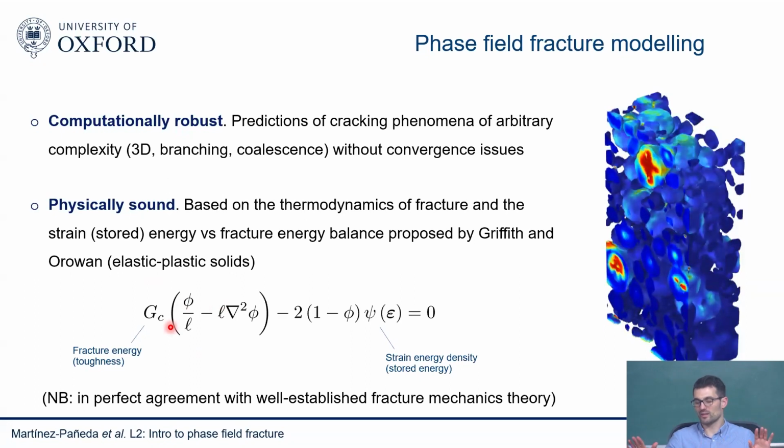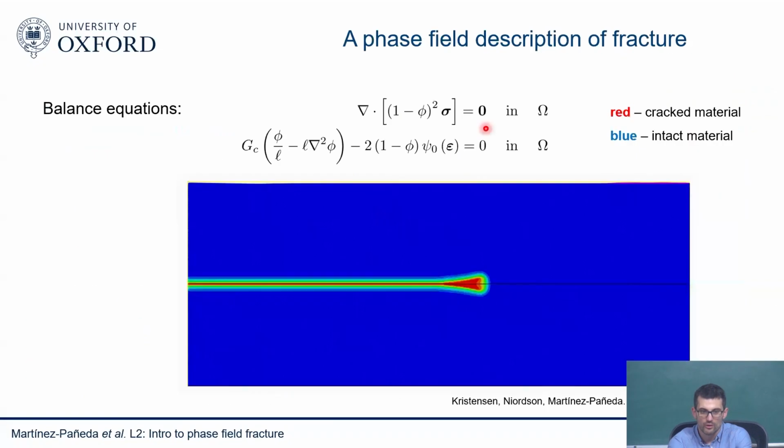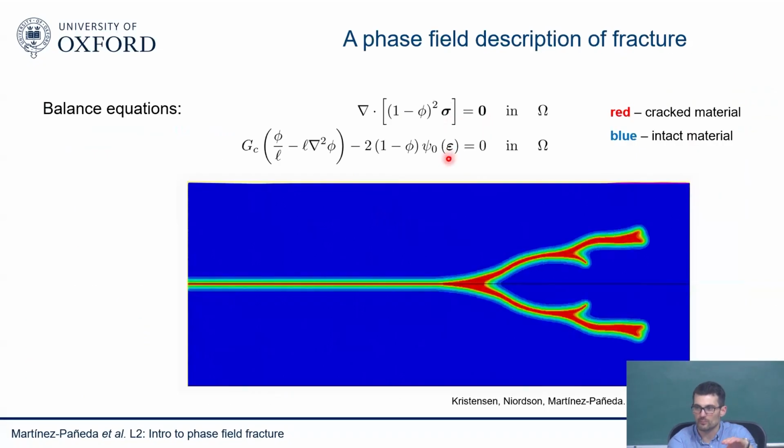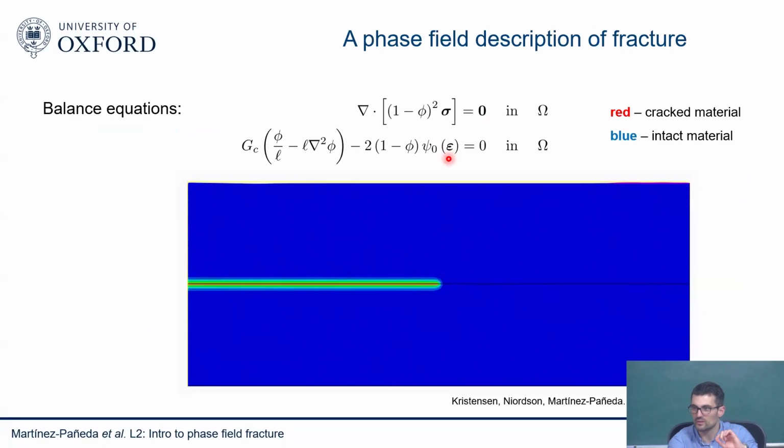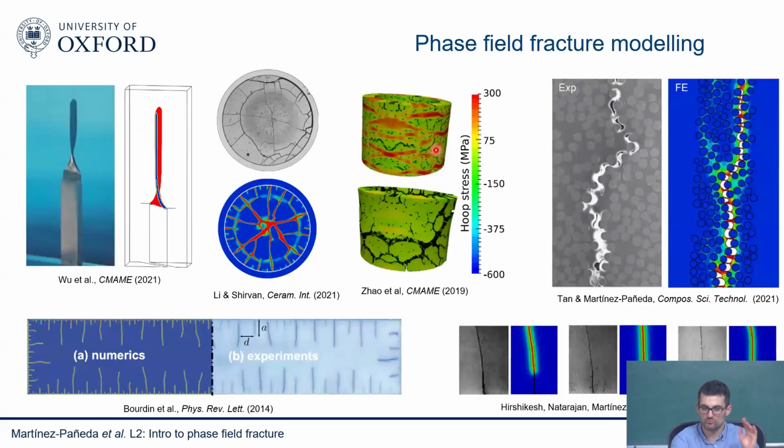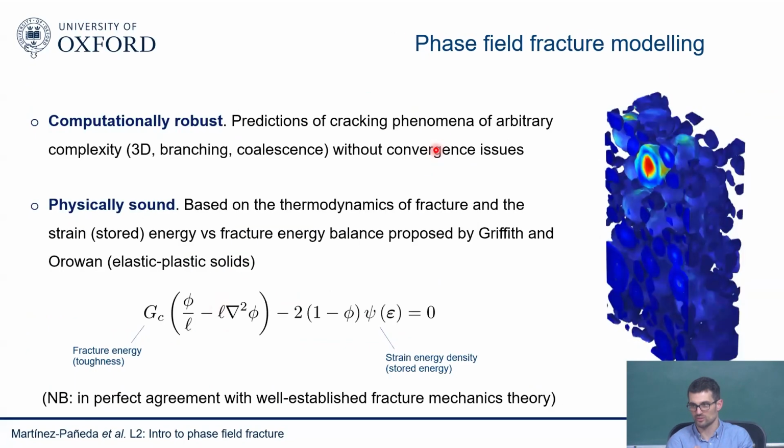On the computational mechanics side of things, there are some benefits related to the fact that we are solving the damage as an independent variable and with a different PDE, because you add some flexibility on the computational side of things. I will discuss that later on. But the short answer is that it's more robust because you solve for the damage variable independently, so you get convergence much more easily. And the other one is that it's connected to fracture mechanics. I don't have 4 or 5 parameters to fit. I just have one, a fracture energy, that I know before I run my simulation. So it's more predictive in that sense, I would say.